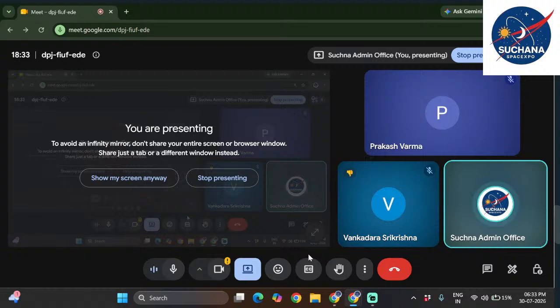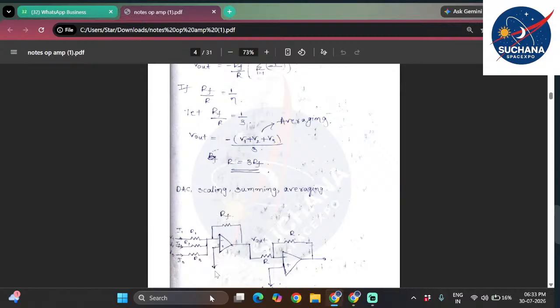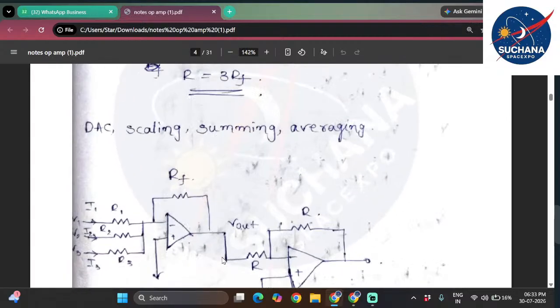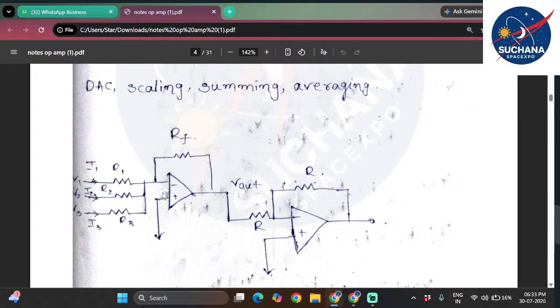Okay. Actually, we discussed pull up and pull down resistors, right? And we discussed the current limiting resistor, maybe in the ECED course. Similarly, there is also something called a compensation resistor; it's just a naming convention. In the actual schematic, we have not connected any resistor to the non-inverting terminal if we are supplying the input voltages to the inverting terminal.